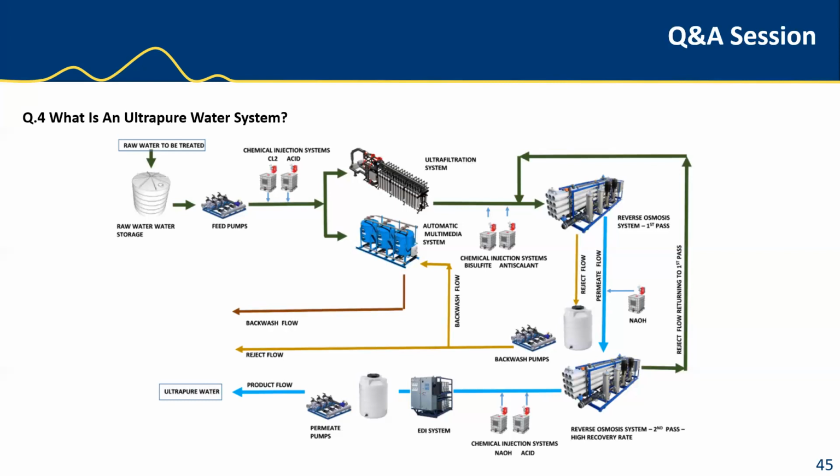Next, the water enters the primary treatment phase. During this phase, the water is passed under ultraviolet light as well as undergoing electrodeionization or a mixed bed ion exchanger to achieve maximum demineralization. To finish this step, you might use dissolved oxygen removal using membrane or vacuum degasification.